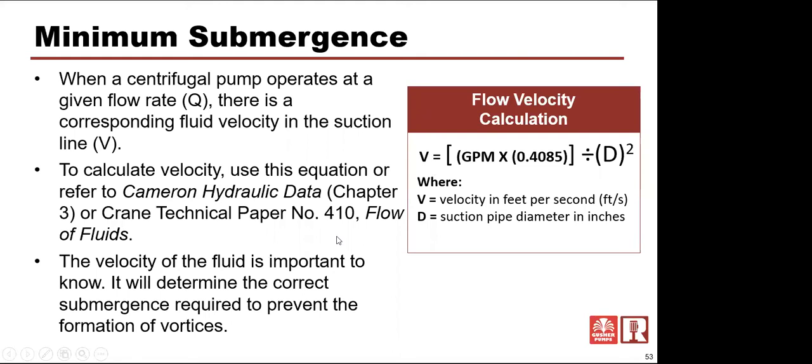Rather than having to do the full calculation of minimum submergence, you do the velocity calculation, look at a chart, and then be able to tell how much minimum submergence you need of that intake, whether it's a vertical or horizontal pump, to the liquid level that's above it. Hopefully I've said that right.